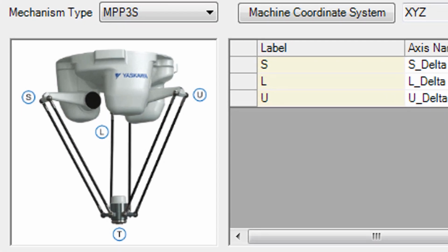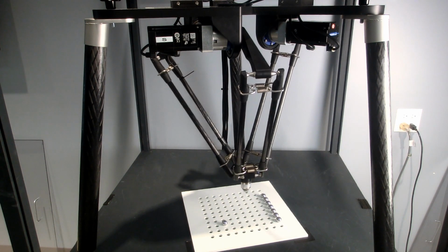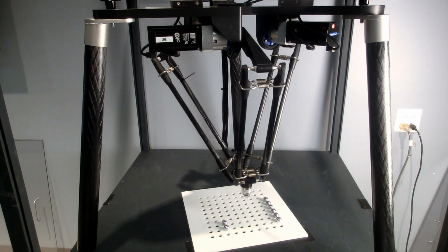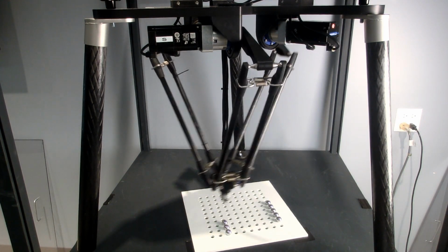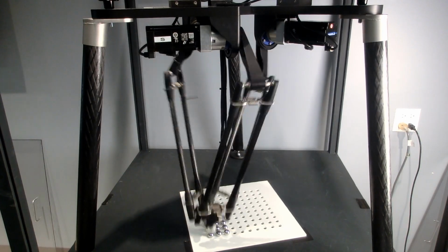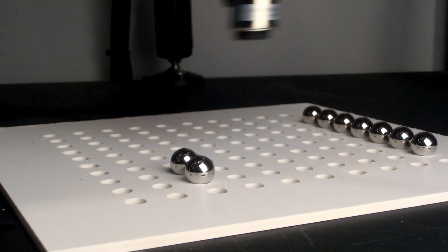A Delta robot has the base on the top and uses 3 motors. Each motor drives a base leg joined to a platform leg, and all the legs join at the moving platform where the tool plate is connected. Delta robots are exceptionally fast, especially with light loads, making them ideal for pick-and-place applications involving small parts.